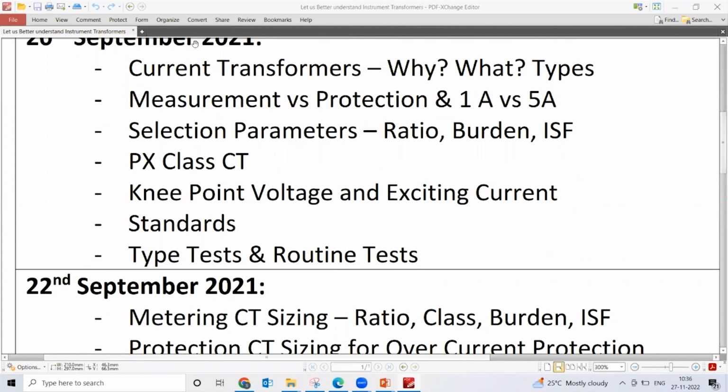Measuring 2000 amps, 3200 amps, 4000 amps, 5000 or 6300 amps is not directly possible, at least commercially it is not attractive, because if a measuring device has to measure 4000 amps, it has to carry 4000 amps, and that's not practically possible.